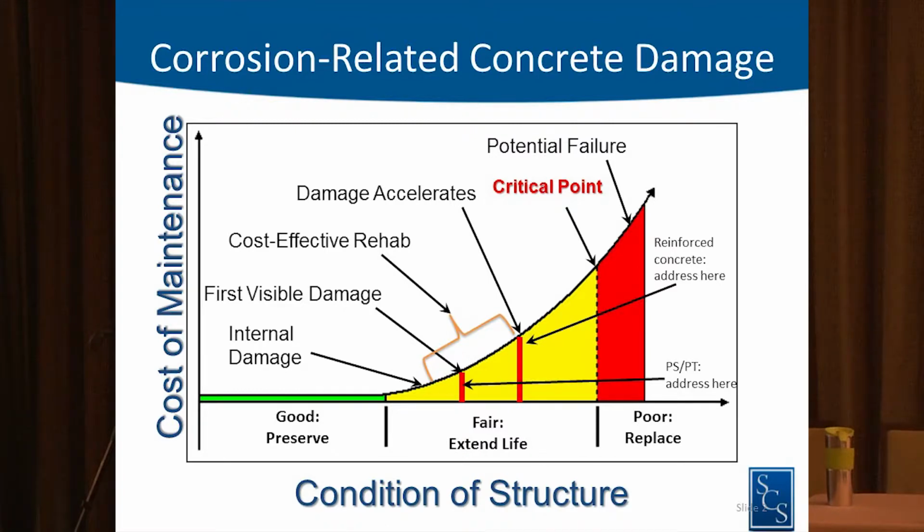We just do the patch and move on. But the patch actually typically accelerates corrosion. The reason, when you have spalling, is because the chlorides are going everywhere. And we'll talk about it.